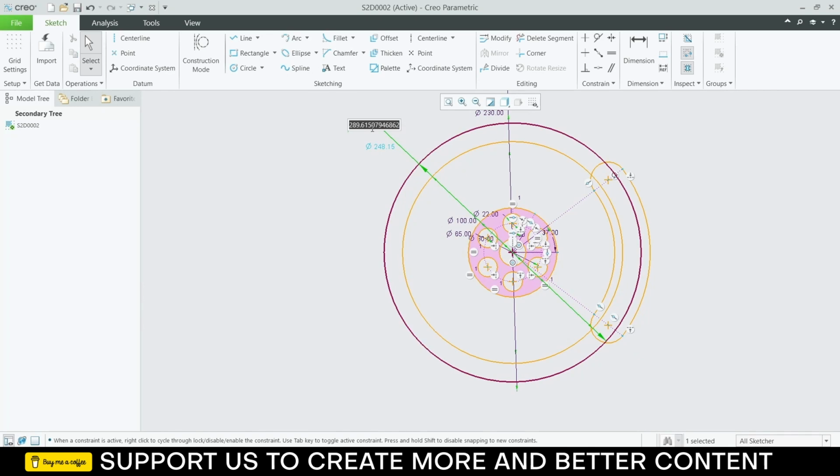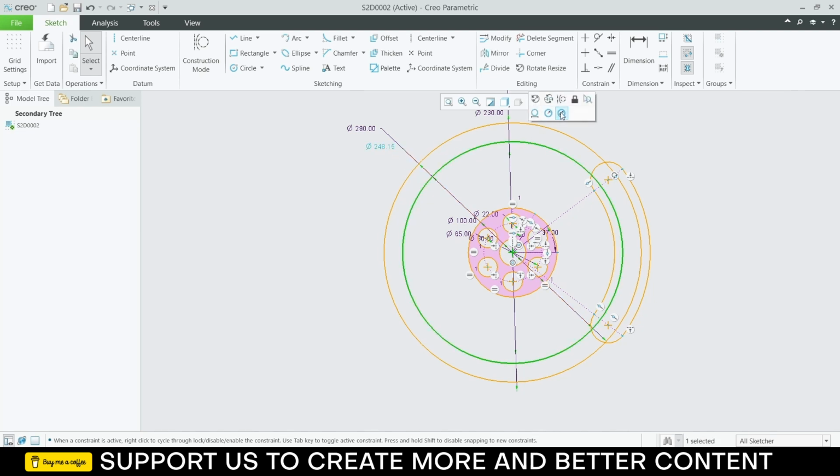So double click on it, 145 multiplied by 2, and for this one, click on here, click on this, and you can type 125 multiplied by 2. Just in case someone says, hey, I don't want to define the diameter, I want to define the radius, what you can do is select the line and click on this half. This is a full one, you can see the arrow on both sides, and this is half.